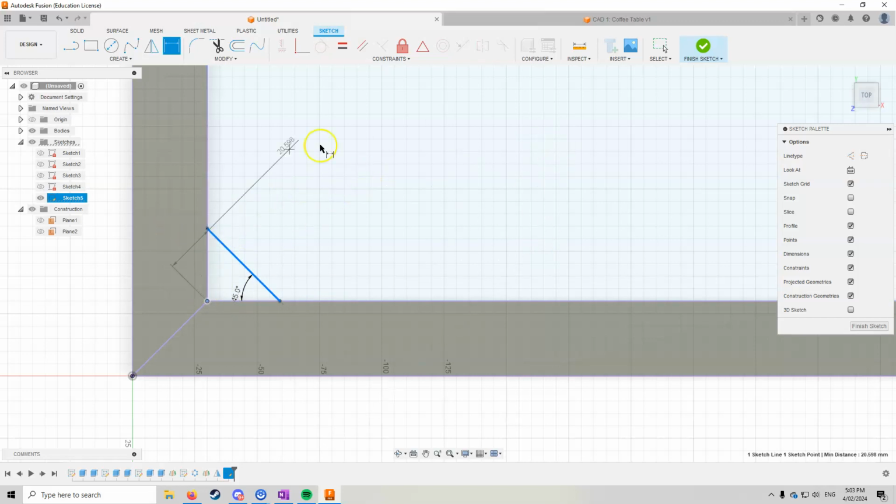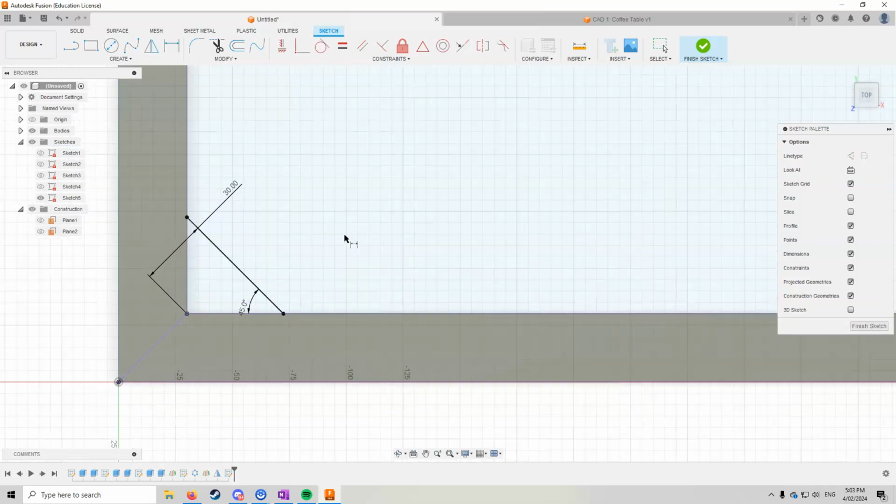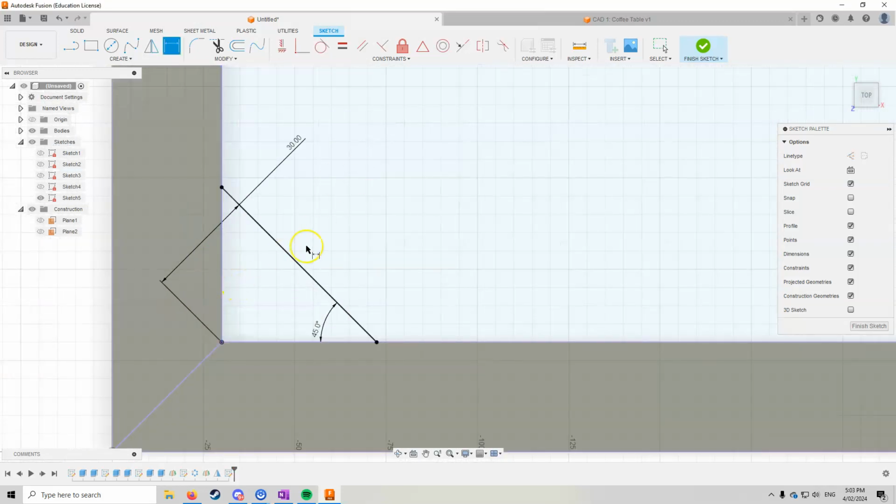I don't have it out. I won't actually move anywhere, so that's perfect. We're going to dimension that at 30 millimeters because if we're using flat bar to create this little triangular section, we've got 30 millimeter flat bar. So if we set this to 30 millimeters, we know that it replicates the material in real life.